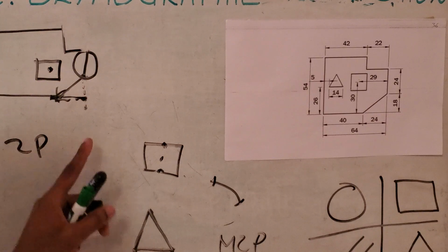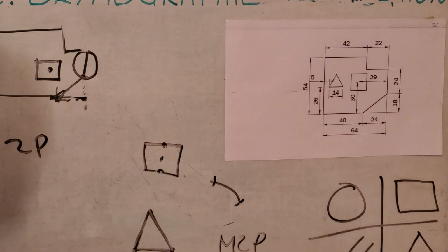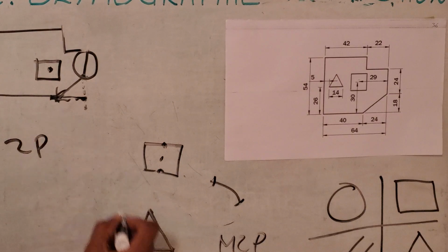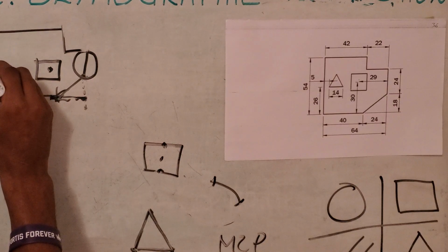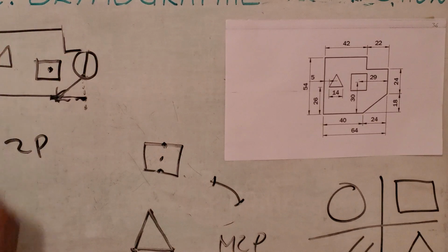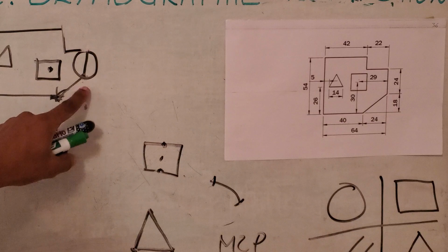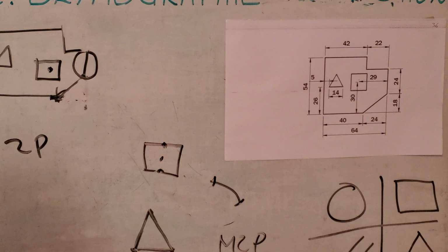Now that we have established that, the next step is to move this into the figure. We M for move, select the object. In this case, we use here as the base point, click, paste it here, and that will drop right there. And that's basically how we draw this figure in AutoCAD. Quick and simple, nice and easy.